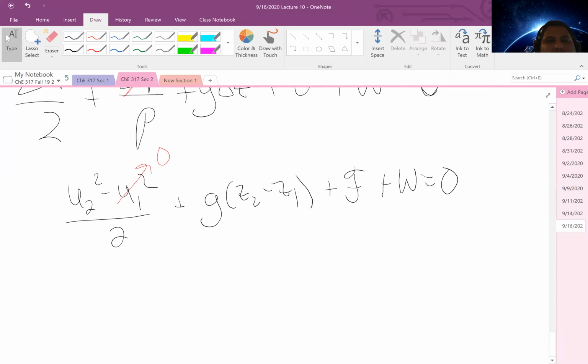However, at the same time, a lot of times in these energy balance expressions, you'll find that friction and the lift are going to dominate the kinetic energy term in these calculations. So sometimes neglecting it won't hurt you, but the more conservative estimation in terms of work and power is to always just consider the energy required to get it moving, the energy required to lift it, and the energy required to overcome any shear and friction that happens during transport.